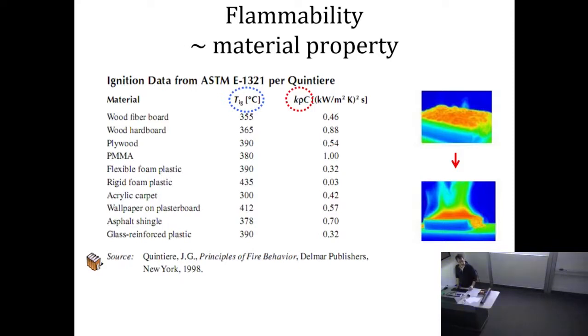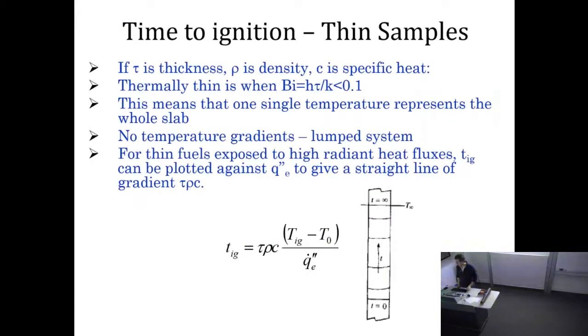Whereas a material that is conductive will not ignite at the surface because it lets the heat go by. And I'm going to show you this, and then we give you a break. Everything that I showed before is for a material that is very thick. It's so thick that it behaves as infinite, or semi-infinite, with a free surface, and the heat will never be able to see the end of the fuel layer. But the other case, and the most dangerous ones, is when fuels are very thin. They are so thin that it is the opposite of semi-infinite. They behave as one single temperature.